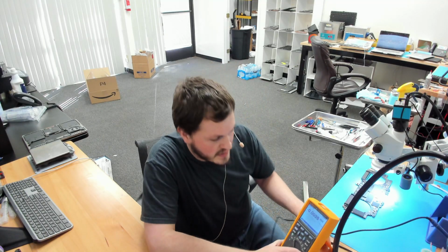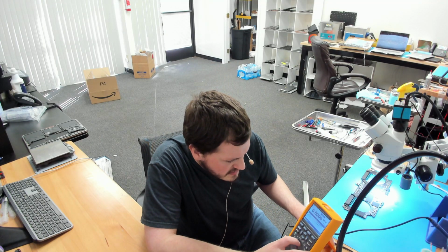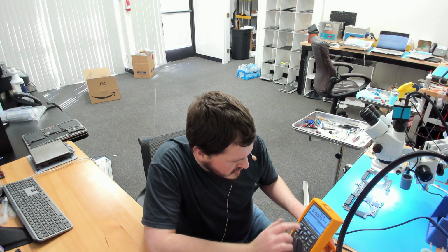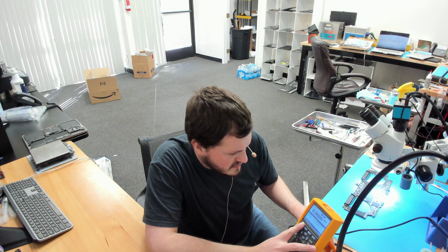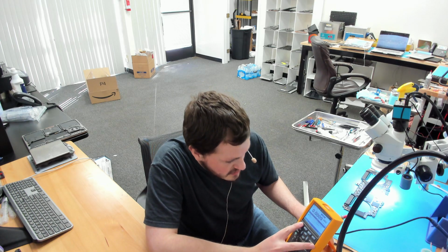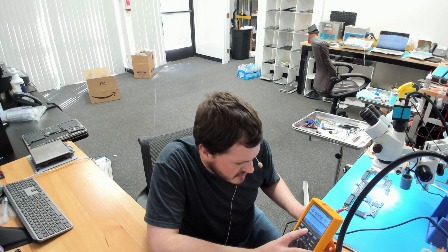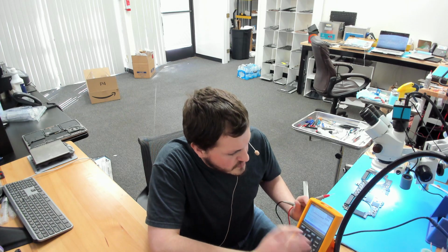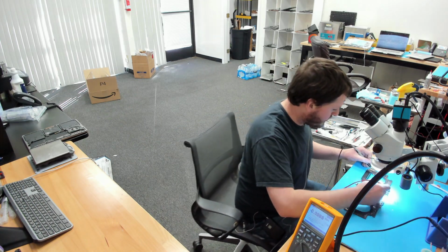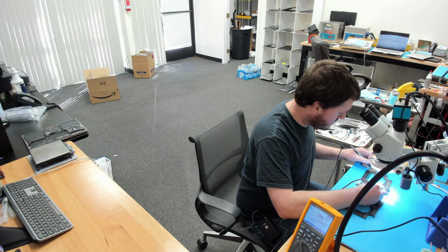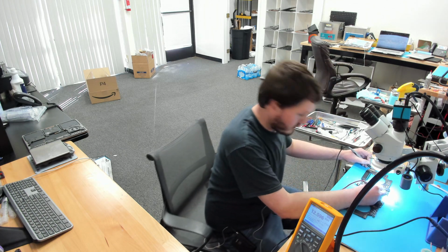I'm going to use the trend feature of my multimeter here to kind of show you guys what's going on here. So we're going to go record. Now this is the Fluke 287 multimeter. It's a little bit expensive, but so far I'm absolutely loving it. I'm going to go ahead and just log voltage on PP-bus G3 hot for 1 minute. So I'm just going to hold my leads here, and we're just going to watch this.